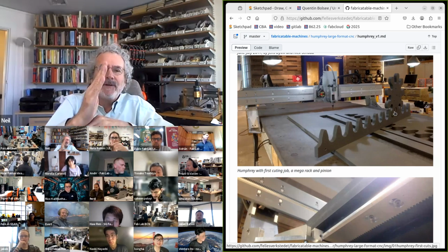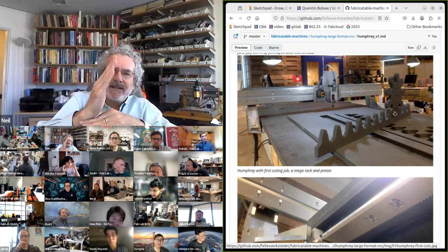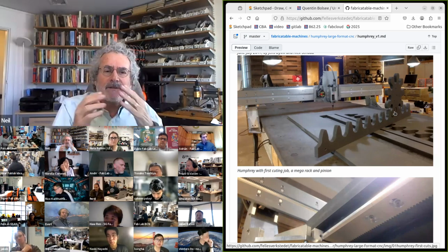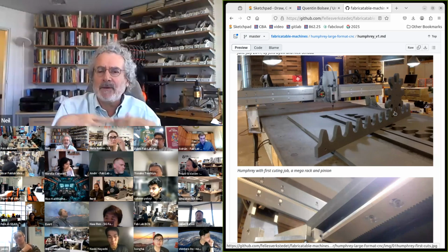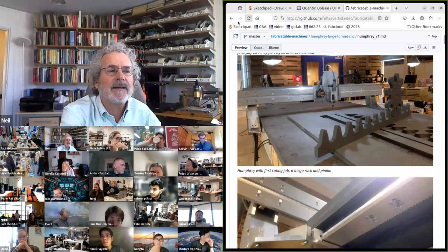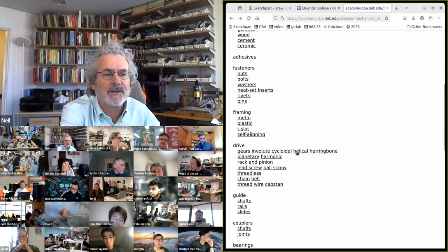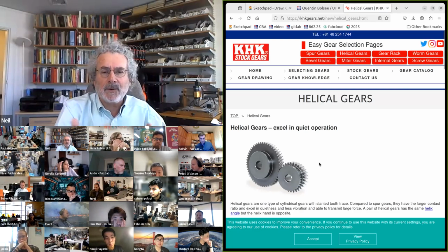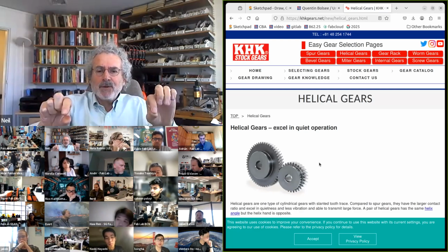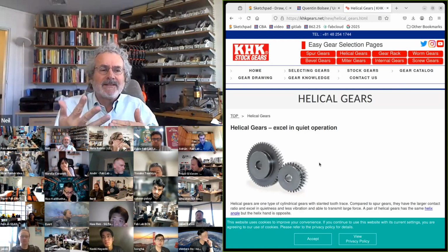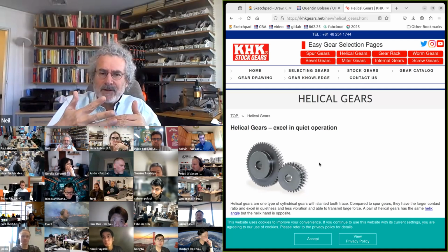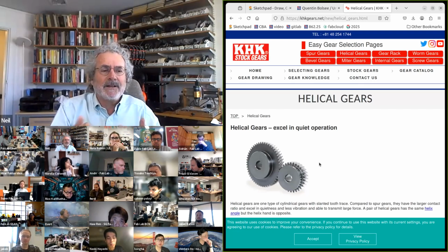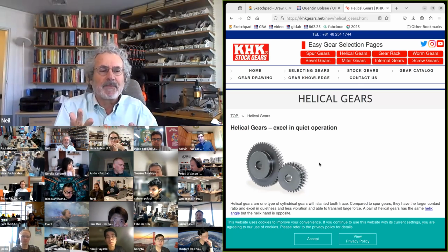The force angle that it transfers, the angle of the transfer is steeper, that puts more load on it. So these can be smoother, they can be easier to make. They're less effective for the force transfer. So far I've just done an extruded gear that has continuous transfer on one point, but it's extended. In a helical gear, it's doing that in 2 degrees of freedom.